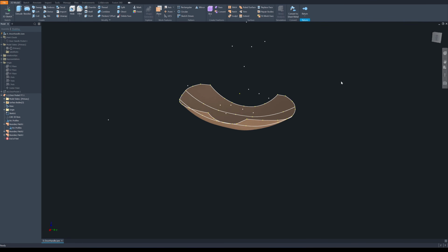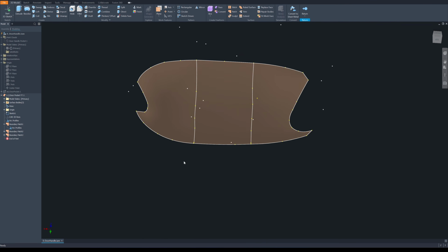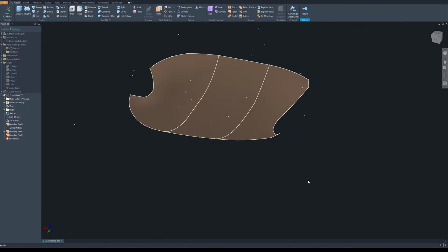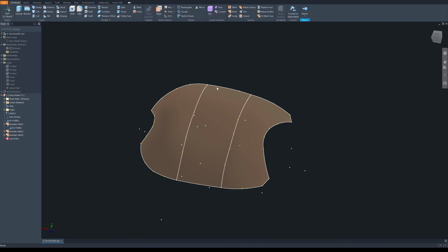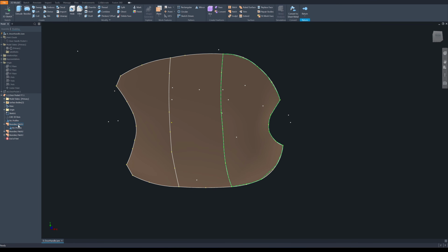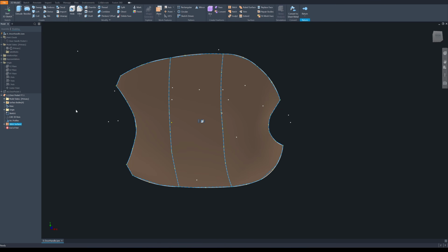Okay, here's how you create a surface with a 3D scanner. If you put more controls, more boundary, you get a more accurate result. Okay, next I'm going to flatten this one. To do that, I'm going to stitch all of the surfaces together. Click on apply, done. So now the surface is stitched.